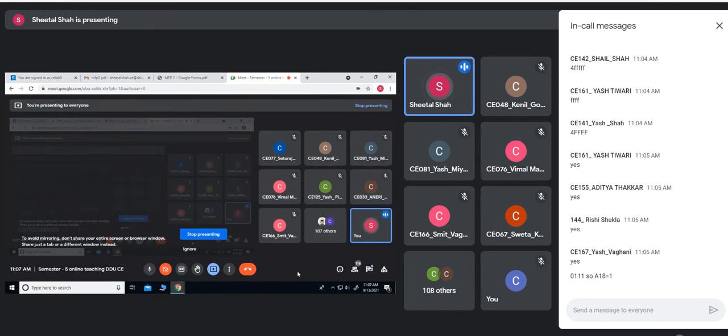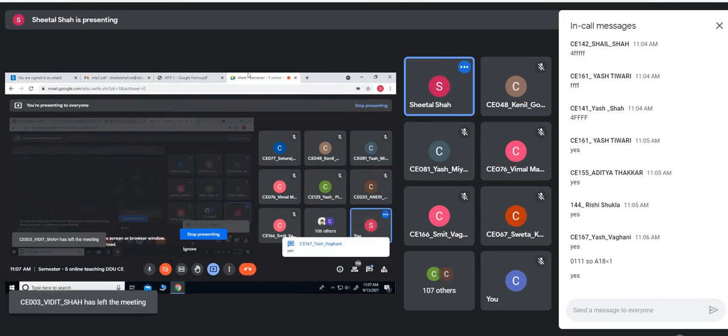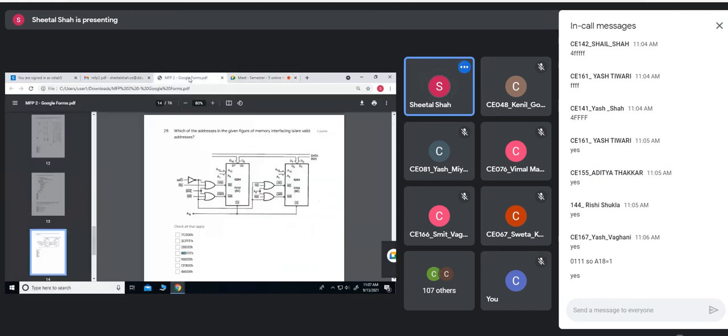Are you getting me? A corresponds to 1010, and hence the second bit is 0 here. Then comes 9. How about 9? It corresponds to 1001, so here also the A18 pin is low. So this is also a valid address.